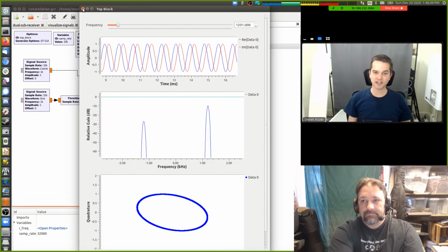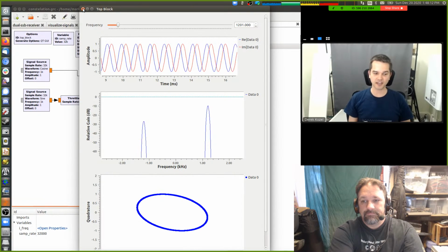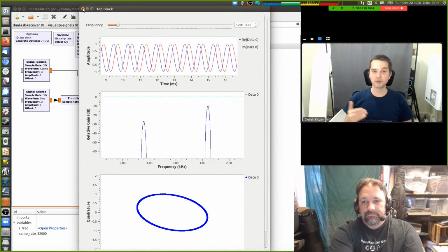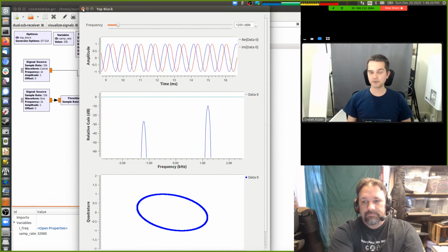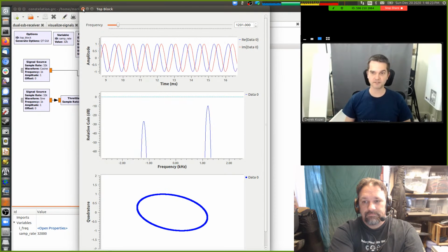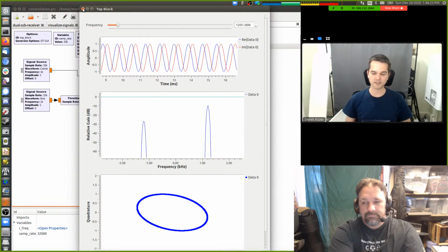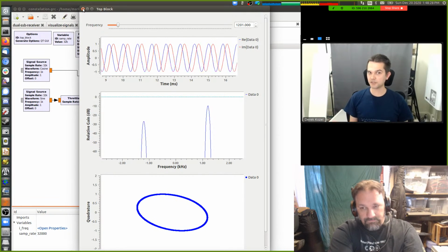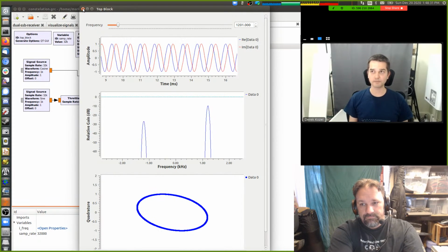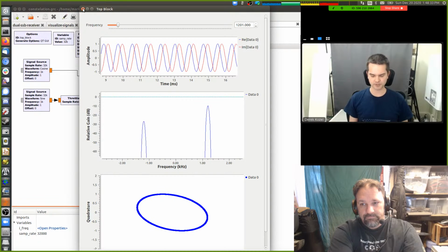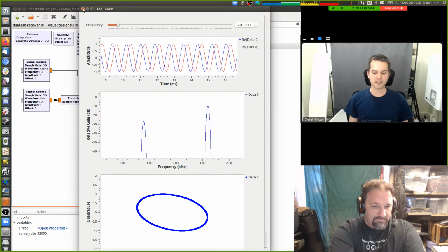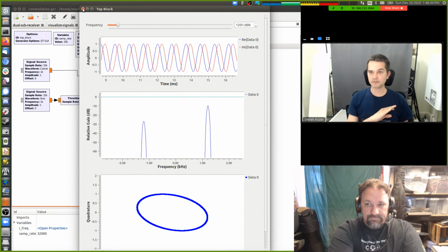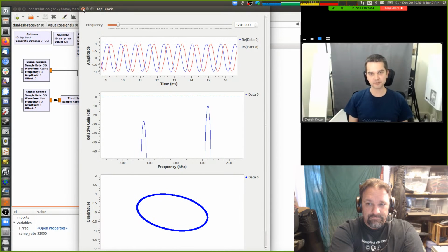Conversely, on the transmit side, you have a DAC, a digital to analog converter, driving a voltage onto the antenna at a fast enough sample rate that you can represent the highest frequency component of your transmitted signal. This is what the Flex radios do for some of their bands. I don't know which ones are direct conversion, but this is literally what they do. They have really fast ADC, they have really fast DAC. And if you're doing that, I think you must do it purely in real value.